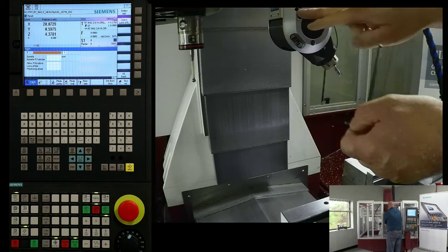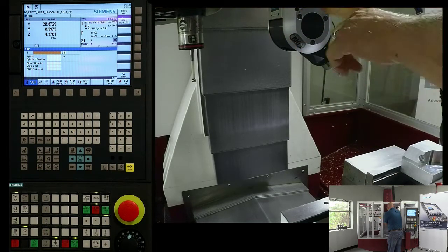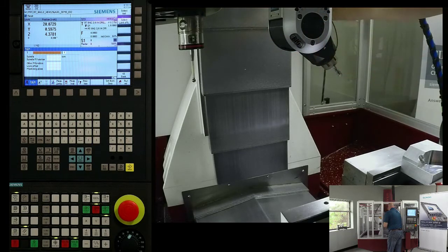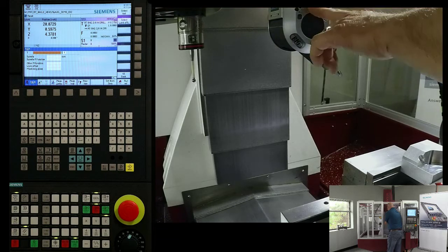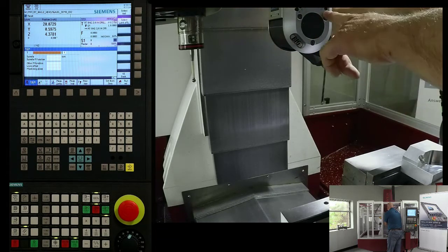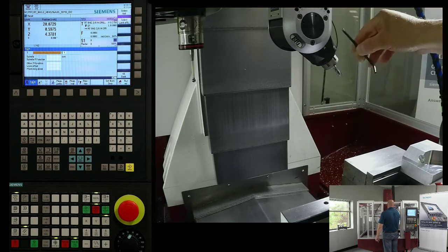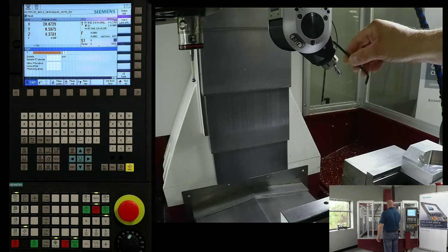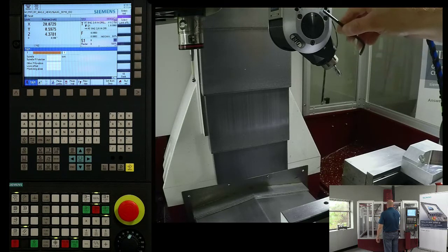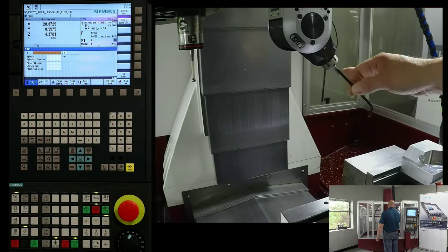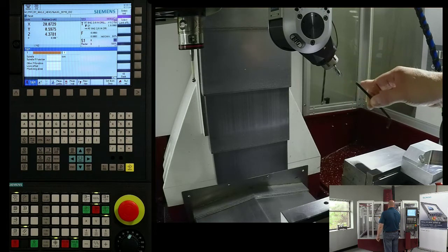And then I'm going to use this set screw, and it's really a precision tip set screw, to bring the tool orientation into a specific angle. So with these, I can get anywhere from 0 to 10 degrees and anything from 0 to 90 with quite a bit of precision. Now, if I needed to be at a value in between a degree increment, then you're going to put a dowel pin in here and indicate across that surface. And that's where having the swivel cycle back in jog becomes really handy.